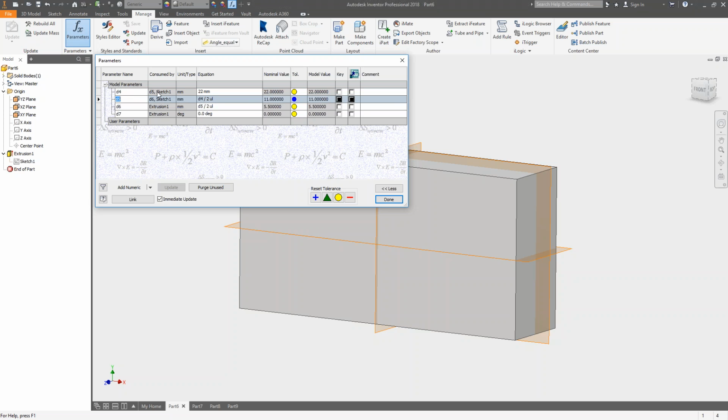and if you remember this first model we did, it shows you where it's used, the sketch. It shows you which sketch it was used in. It'll tell you what extrusion it's used in, and it lists all of the math. If you happen to do some formulas, you can see, D4 divided by 2, 22 millimeters, D5 divided by 2, but you can create your own and use those for creating your model.